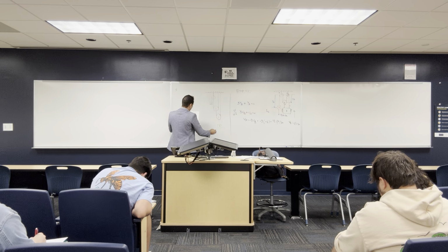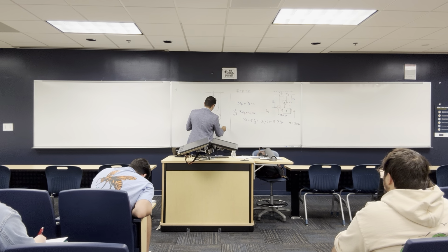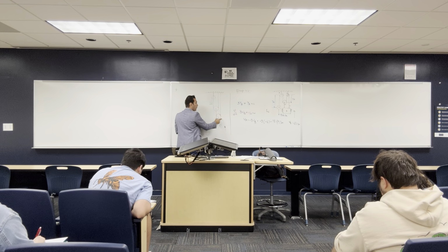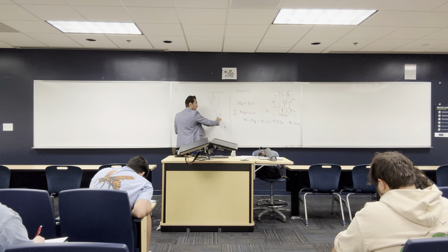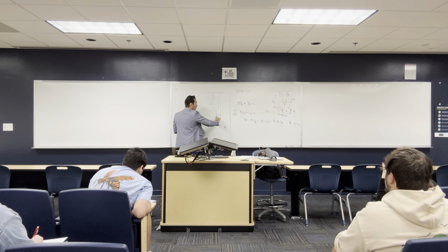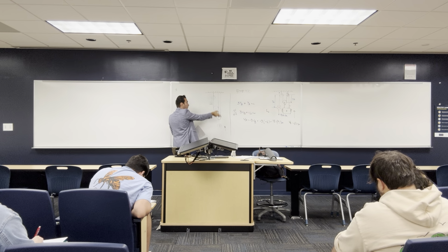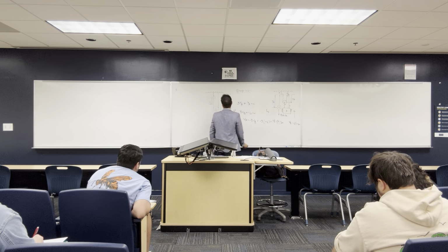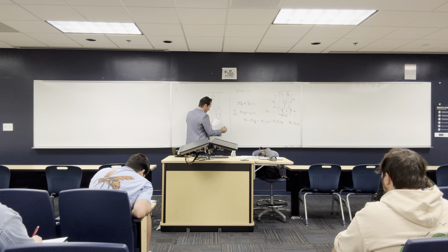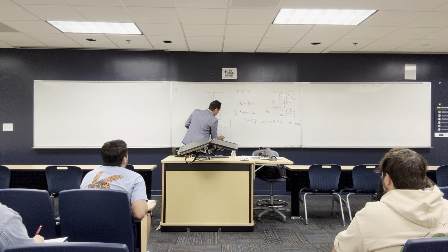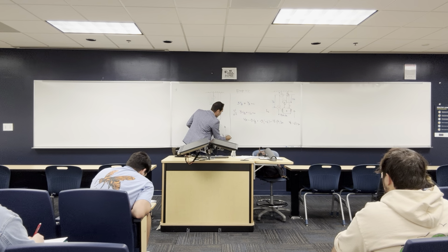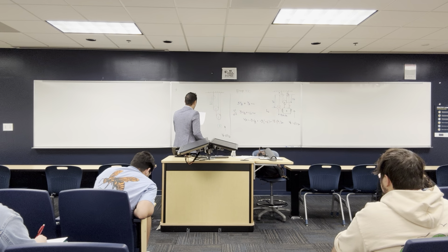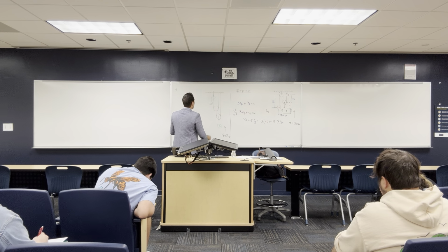I told you in this problem that the velocity VB is going up. By the way, the velocity of B is the same as the velocity of the pulley. Why? Because they are attached to a constant length cord. So they either move up together or go down together. They are not like here. So, okay, VB is 6 feet per second, going up. All right, so what I'm asking here, what is the velocity of A?